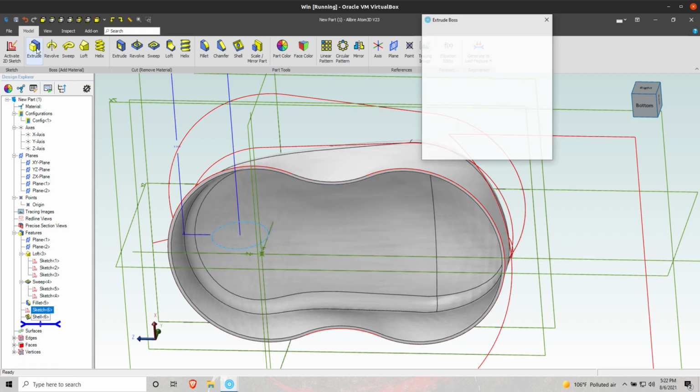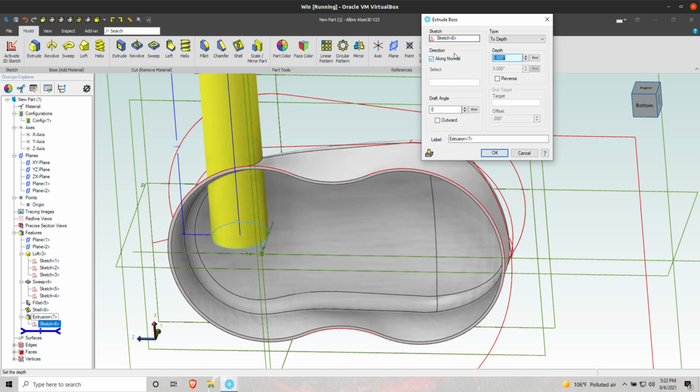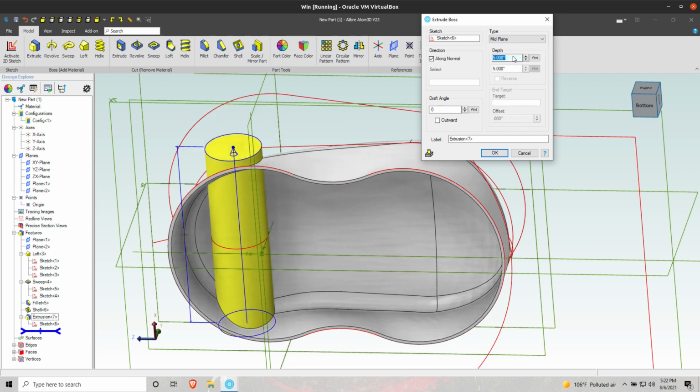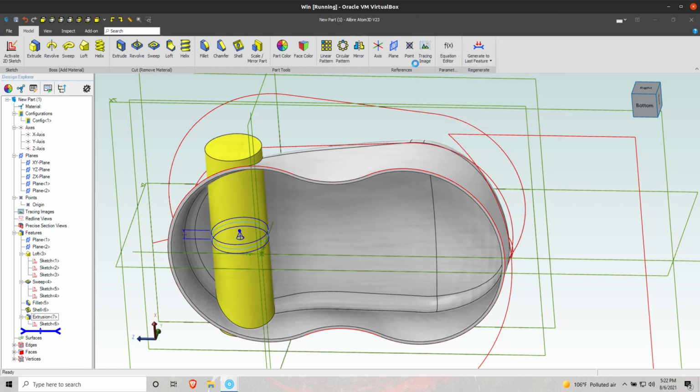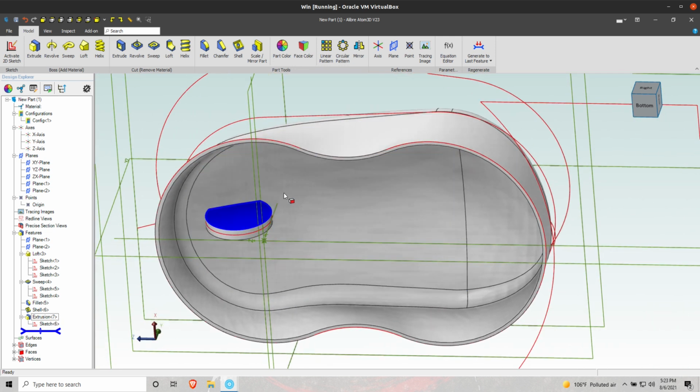We'll extrude it to make the scrolling wheel, and that will be mid-plane, I think. Go to a depth of something like 0.25. Fantastic. Now, since we're making the impression of a mouse, you'd probably have some assembly in here that reads the scrolls of the wheel or something.